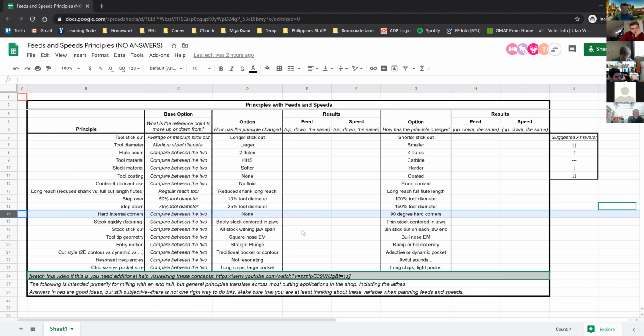Yep, I totally agree. But to Luke's comment, it's actually something you really want to think about. What do I care about most? In the case of the ShopBot, I don't want to sit there for literally 8 hours while I do one pocket. So I'm going to abuse the tool a little more and get out of there 7 hours quicker.